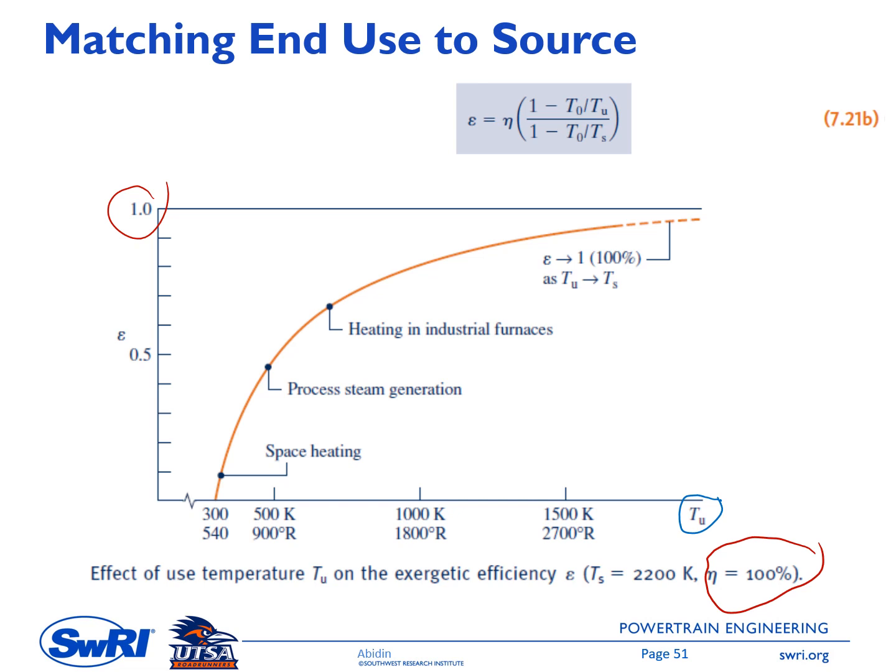So this is a temperature close to the combustion. Combustion temperature is usually like 2500 Kelvin or 2600 Kelvin. But if you put more oxygen or more EGR, exhaust gas recirculation, which you can learn in more detail in the internal combustion engine subject, the temperature can be lower, to 2200 Kelvin. Okay, back again to this chart. So we have Ts